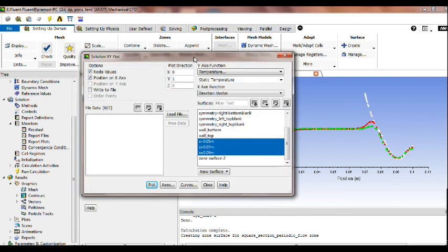So now we have seen the problem of periodic heat flow. In this tutorial we have seen the periodic flow and heat transfer in a staggered tube bank modeled in Ansys Fluent. The model was set up assuming a known mass flow through the tube bank and constant wall temperature. Due to the periodic nature of flow and symmetry of the geometry, only a small piece of the full geometry was modeled. In addition, the tube bank configuration lent itself to use of a hybrid mesh, with quadrilateral cells around the tubes and triangles elsewhere.